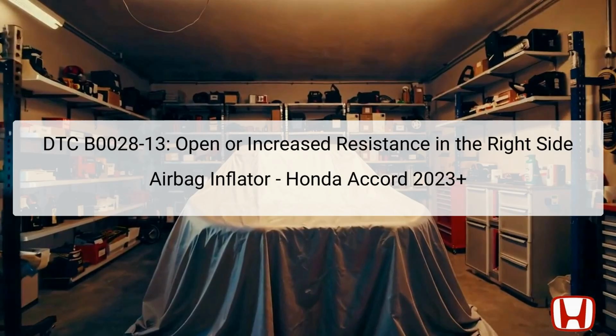occupants of the vehicle. If there's an abnormal voltage detected on the line associated with the Supplemental Restraint System (SRS) unit, the system flags this issue by storing the DTC. This can compromise the integrity and functionality of the airbag system. Prior to this diagnosis, one should verify whether the vehicle was involved in any collision incidents, which may have affected the airbag system and related components.